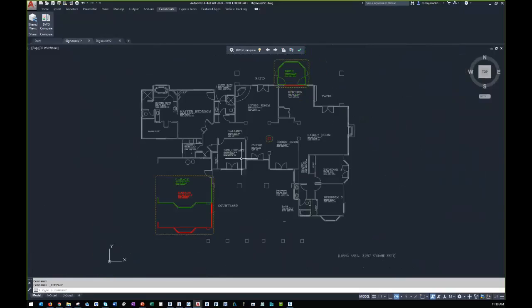And in order to highlight the new or enhanced part of this compared to the previous DWG Compare, there are a couple of new icons that you can use up here. One of those is going to be Import Objects. So you can import the objects directly from that compared drawing if you want to apply those changes to your file. So you have that access right there in your session to not only compare the two drawing files, but actually incorporate the changes as well.